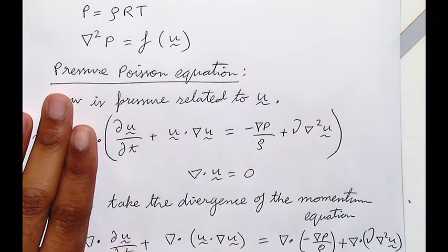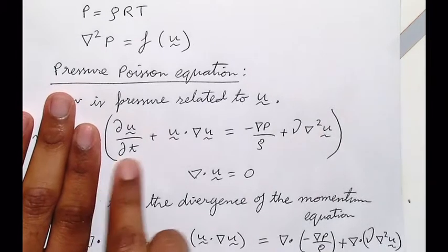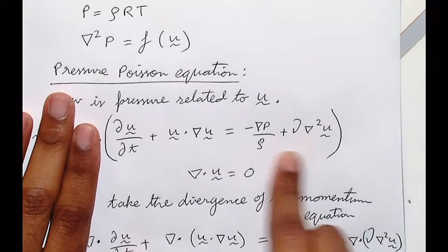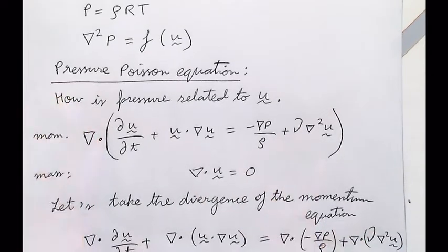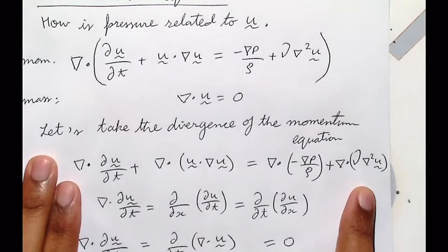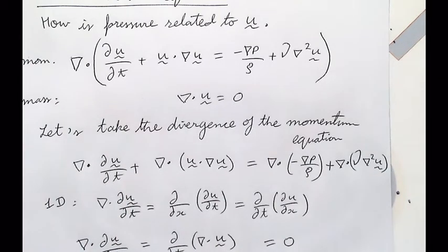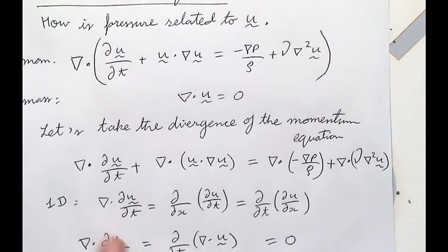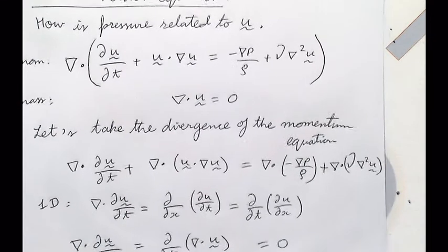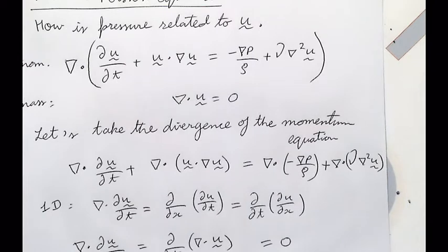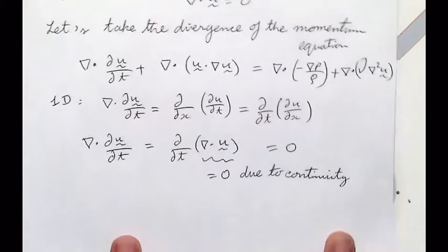So this term is a conservation law. There's no assumptions in here. If we take the divergence, there's still no assumptions in here. Yes, this whole thing is still perfectly valid. And when we interchange the derivatives, again, we did not make any steady assumption. The argument inside is equal to 0. So there's no point taking the time derivative. There's no steady assumption.